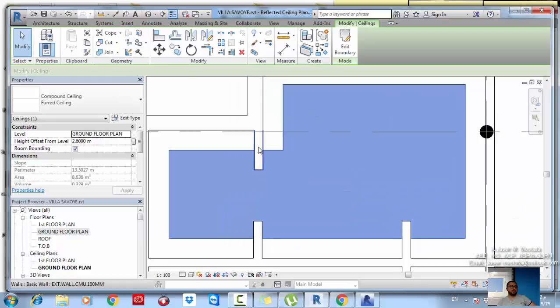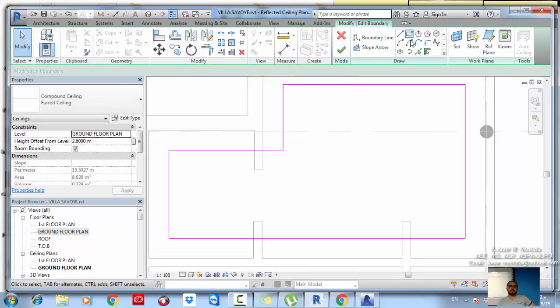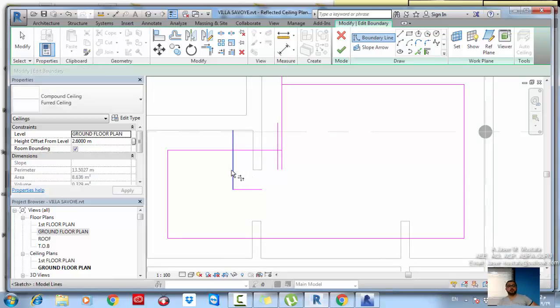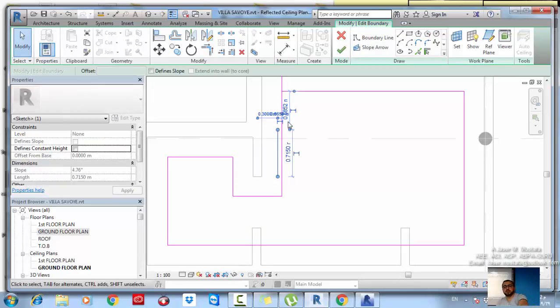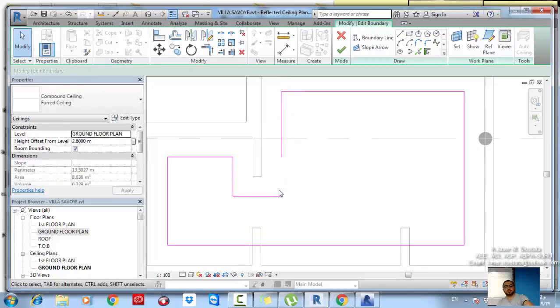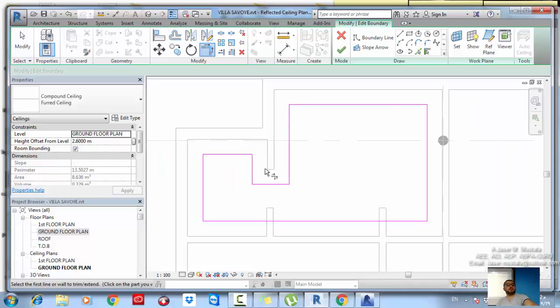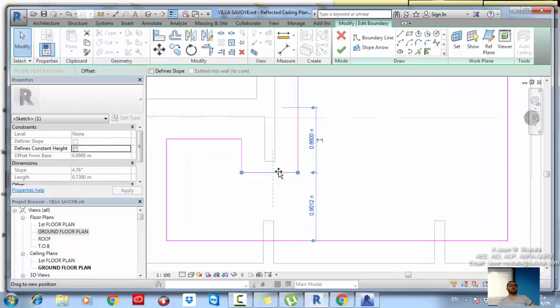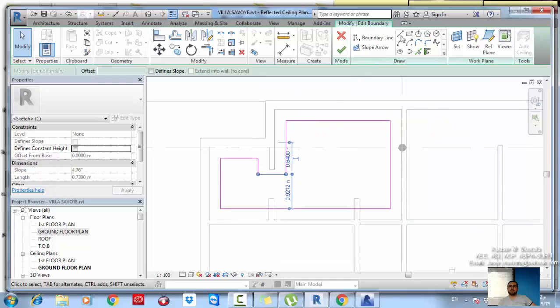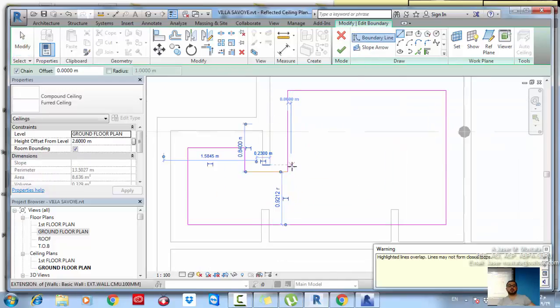You have this wall, so you can just click this, pick line, give it an offset from the initial point of drawing, 0.3. Fine? This way, sorry, and this line, trim, 1, 2, 1, 2. You can just delete this one, trim. Don't create overlapped lines because it will not enable you to create the option, okay? If you have two lines overlapping, it says it's overlapping.